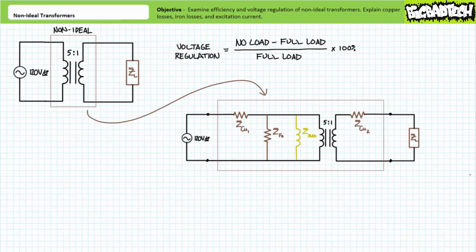The origin of this voltage drop is the small but measurable resistance of both the primary and secondary windings internal to the transformer. In a sense, voltage regulation is a current-dependent phenomenon that occurs in two stages. Recall we earlier observed current drawn by the reflected impedance and the parallel leakage paths must travel through the resistor accounting for the internal resistance of the primary windings, and as such, a small voltage drop occurs.